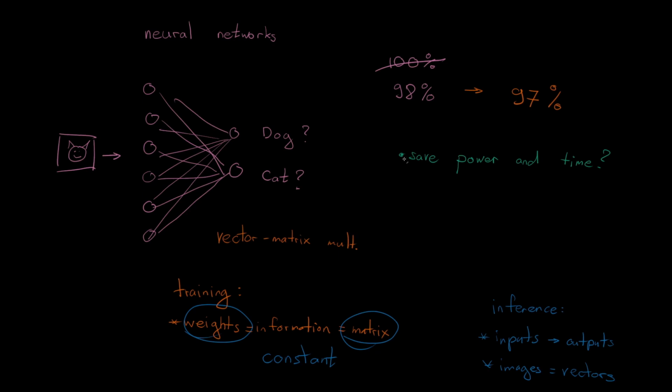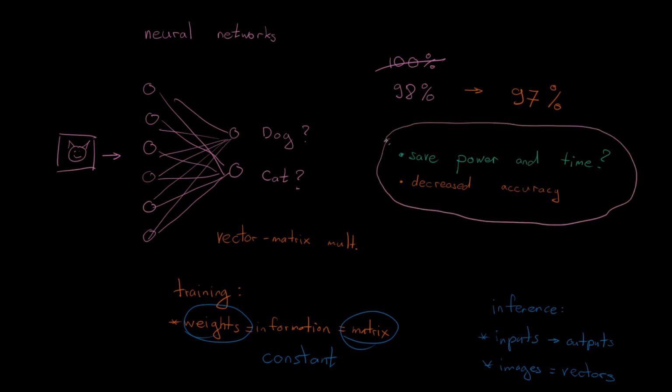And of course, the con is that we have decreased accuracy because the precision with which we can program these devices with a certain conductance and the precision of the voltages we can apply, of course, is not as good as dealing with digital logic with transistors in modern computers. So this is a trade-off that we have to think about if we want to use these kinds of circuits for computations like vector matrix multiplications.